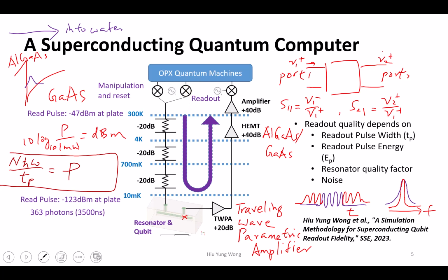Based on what we just talked about, the readout pulse, if you have a certain SNR, that dictates how much integration time you need, which dictates how wide your readout pulse is in order to detect. Now, if you use a longer pulse, that just gives you more signal, and when you do averaging, you get a much better measurement fidelity. But there are two things happening here: the spectrum and how it interferes with other hardware, and how much readout fidelity you want out of the system. Are those two tied together in determining the pulse width for the readout?